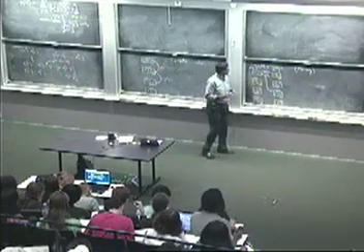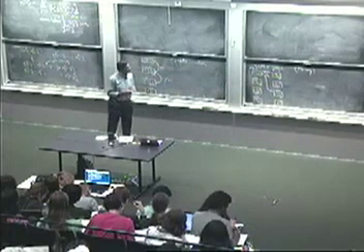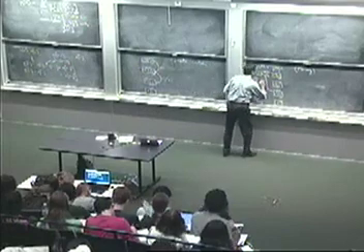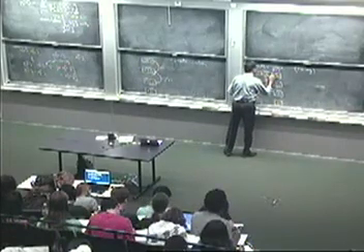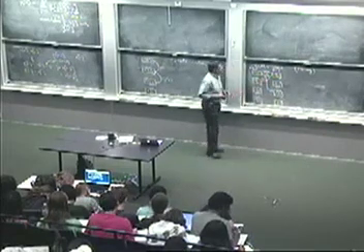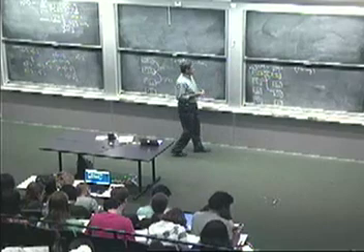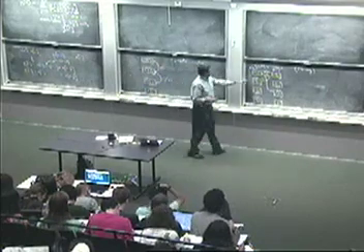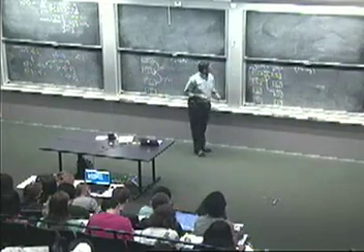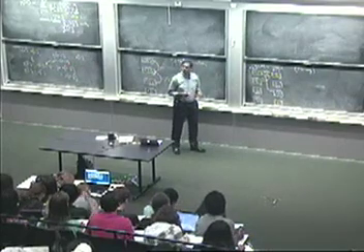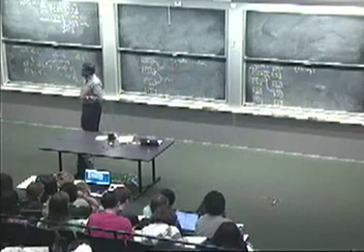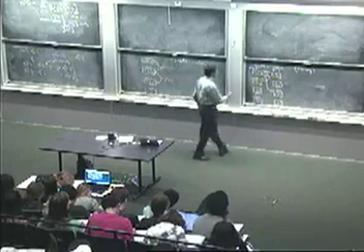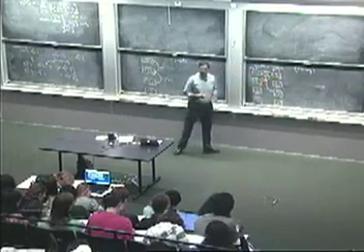Let's do it for one more case. We're in 0,1. What states can I transition to? I could go to 0,0. And I would do that if my input was 0, right? And what would my parity bits be? Well, that's another case for us to look at. If our input is 0 and we're in state 0,1, what would the parity bits be? For this choice of parity bits, it depends on what specific choice you made, of course. 1,1? You agree?